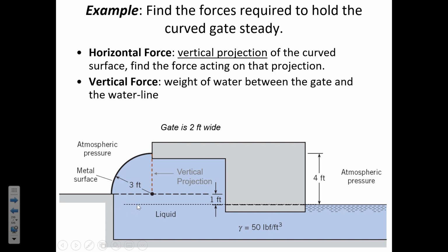Okay, so then when we go up, what happens to pressure as we go up through a fluid? It decreases. So the pressure is negative in gauge terms. Now, it's not negative in absolute terms, not necessarily, but it's negative in gauge terms. And so it's suction. So the higher we get in this fluid, the pressure is becoming more and more negative.